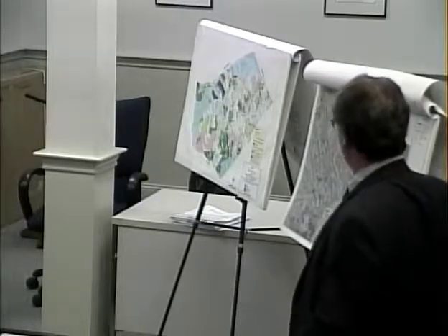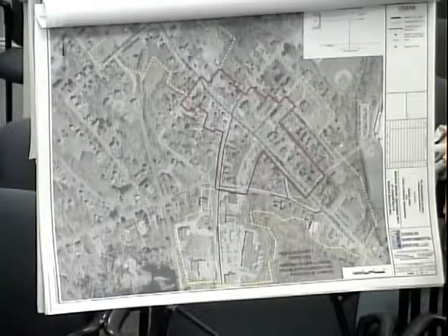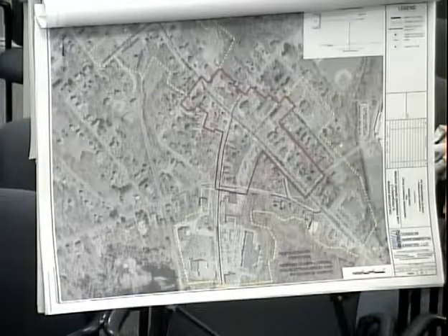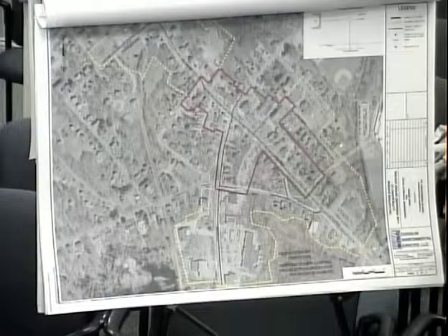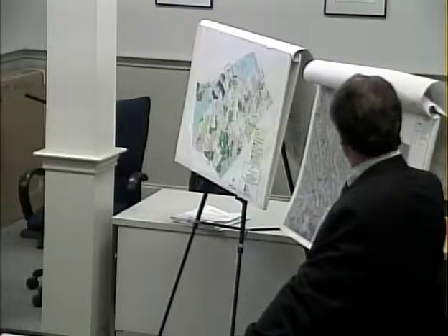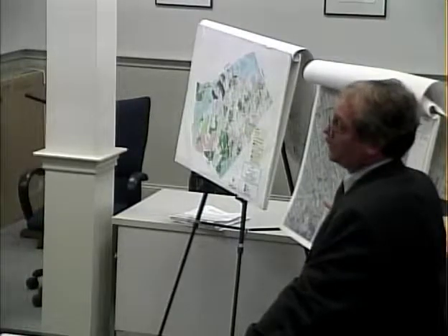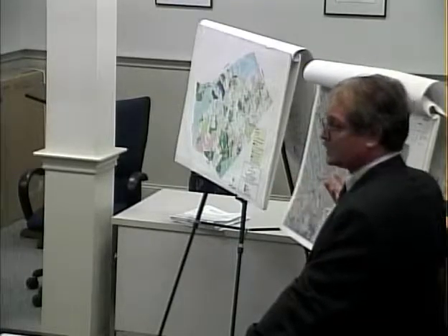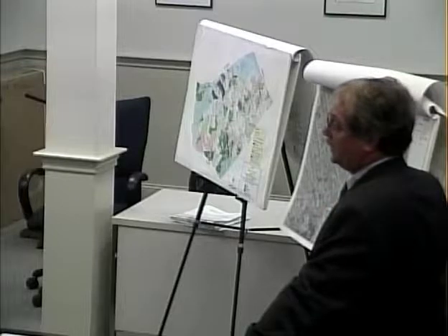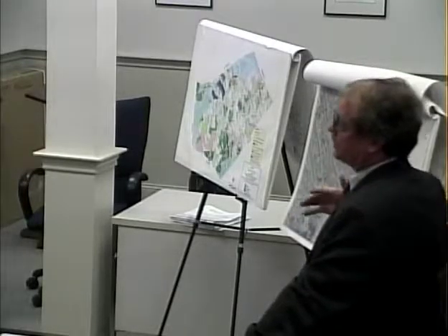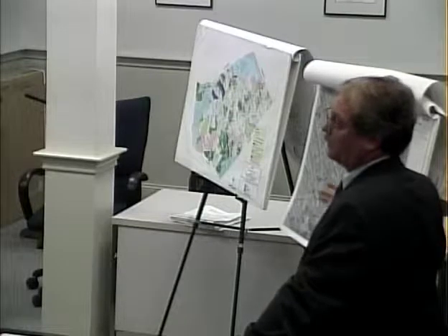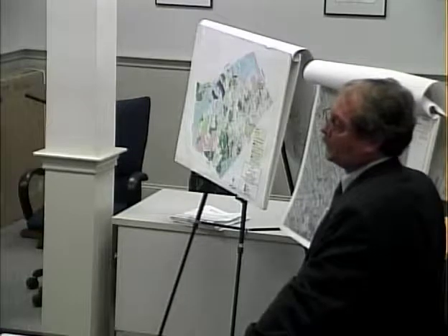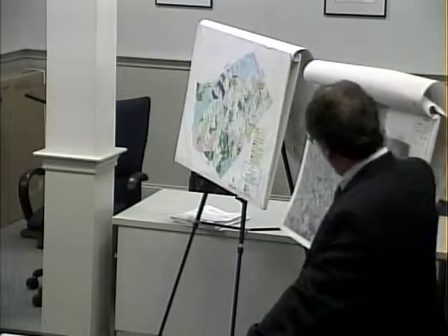Low pressure sewer, I've done a lot of low pressure sewer work, and I like the method. You've got a small diameter pipe, you can go up, you can go down, you can go around. Basically, it's all a pressure sewer system. There is a responsibility for the homeowners to install individual grinder pumps. But that works out fairly well. If their septic systems are in the back and they want to go to the front, it's a lot easier for them to do that. You need about 4 to 5 feet of cover, depending on your community as far as frost depths. Typically 4 feet is enough because you have warm wastewater inside the system, but at least 4 feet of cover for your piping, and you can convey that through a pressure sewer system.